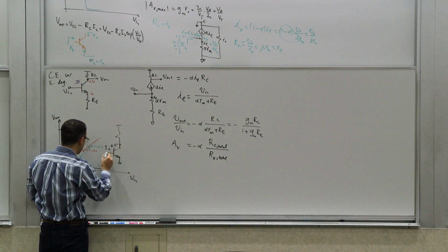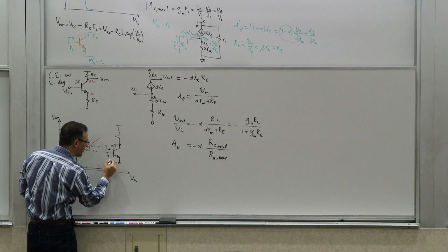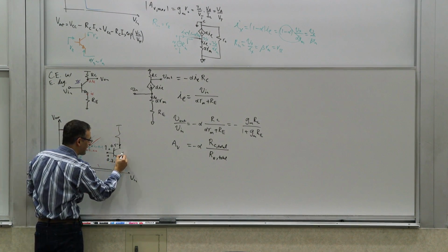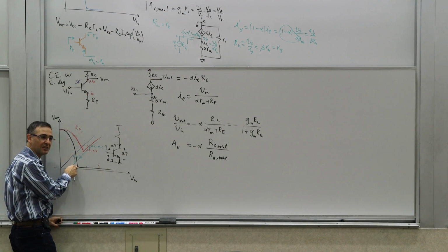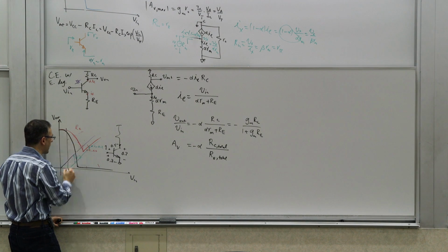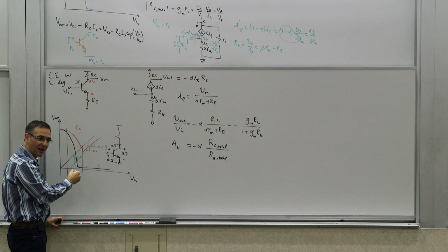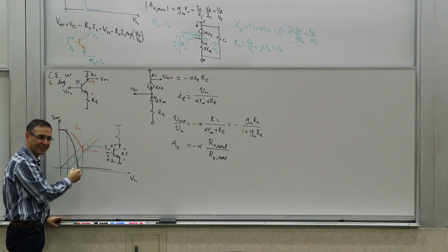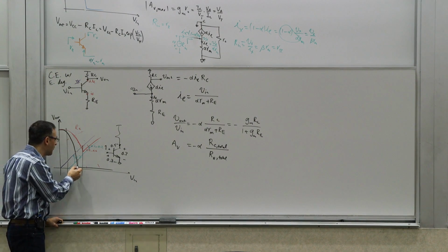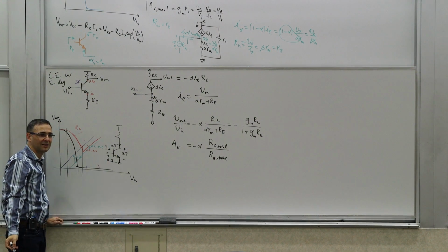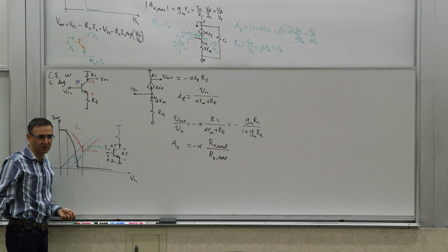But at that point it means this voltage has already reached, because this is also 0.7 above this, which means that this is 0.2. So it already has to have reached here. So this happens much quicker. It is happening, but before that, because now the slope is higher. It has much higher gain. So the argument does apply. It just happens by the time it gets down to the bottom. And that's the definition of saturation.